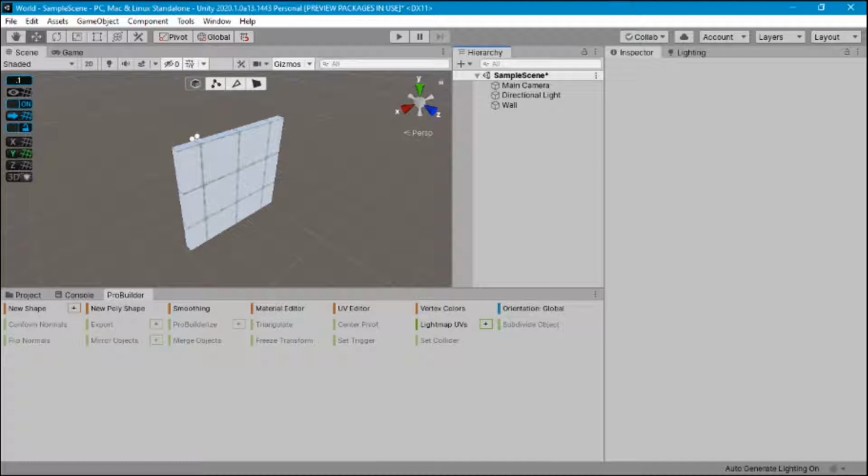This is part 2 of building your own tile system with ProBuilder and Unity. On the previous episode, we learned the basics of ProBuilder, created our first 2 tiles, and talked about overdraw and the potential performance issues we might have when building levels using tile systems. In this episode, we'll create a few more tiles and learn how to optimize them to minimize overdraw.